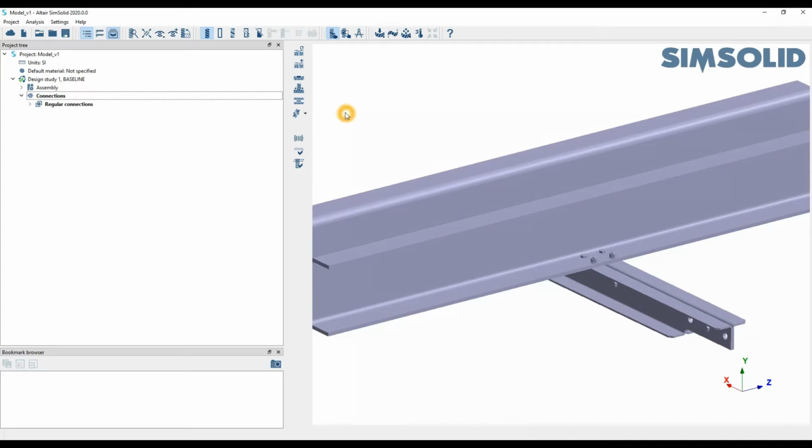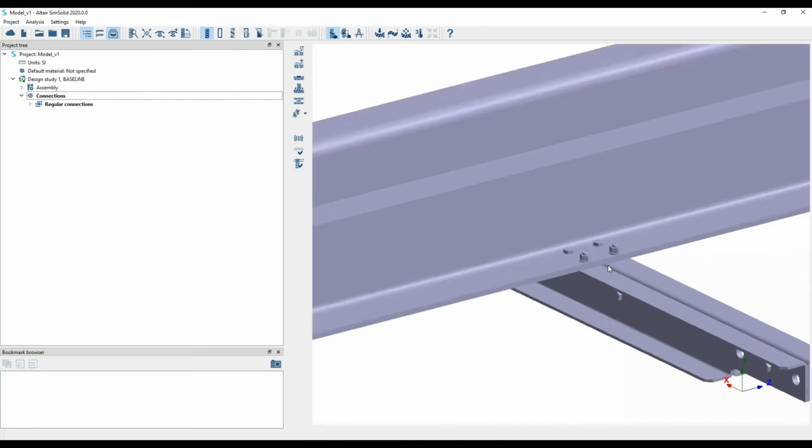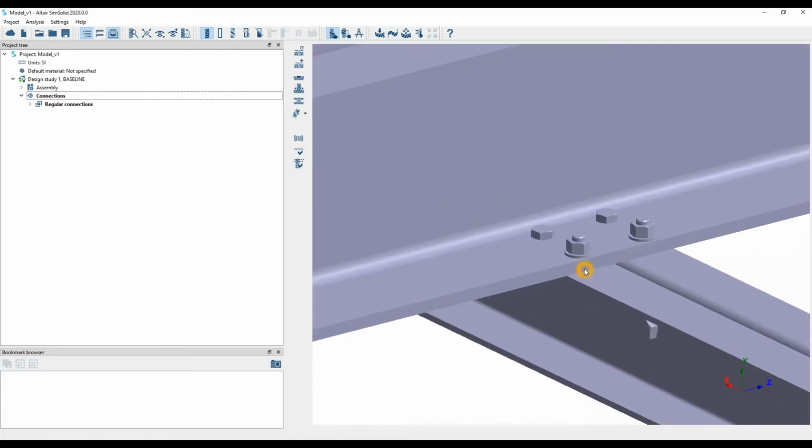If you want to incorporate any sort of welds, you can create spot welds, seam welds within SimSolid. You can also create adhesive connections from the solids itself, so if you already have your adhesives drawn up, you can specify different solids being adhesives. And obviously, better yet, you can actually also implement any sort of virtual connectors.